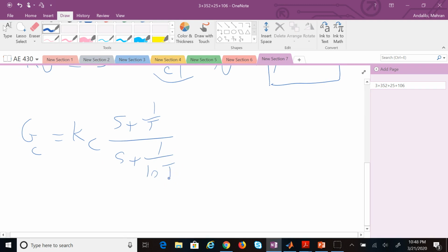Now, how do we choose them? Again, the other requirement is both of these, pole and zero, should be very close to the origin. Both of them. Although one is 10 times closer, if you choose the bigger one very small, the other one would be even smaller. So what I choose is a small number for the zero, which is a little further away. And what I choose for this pole is arbitrary.